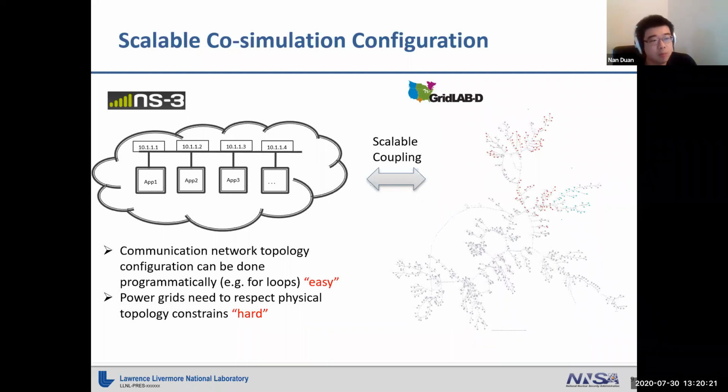And this restoration problem is for distribution grid. We would like to figure out a good way of using those renewable energy resources, or in a wider sense, using distributed energy resources as jumpstart units, and just from a bottom-up direction, restart the distribution grid and make sure the load and generation match, so that once they are reconnected to the transmission grid, they wouldn't introduce too much disturbance.